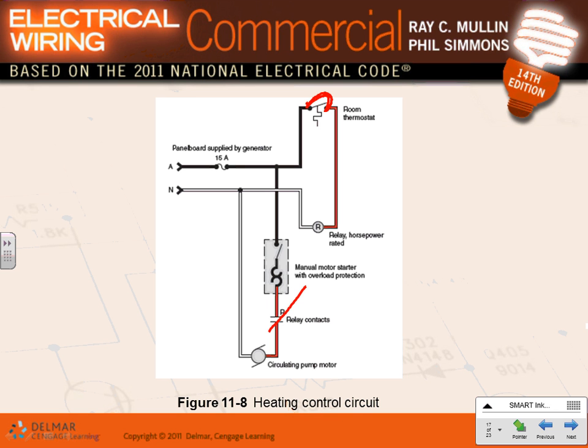So first the thermostat has to call for heat, close the coil. Now the coil is energized. This will close the contact. Now the pump is pumping hot water into the insurance office. Inside the insurance office, guys, it goes to a radiator. It's like a radiator. Then there's a fan that blows air right through it, and you got yourself hot air, or an air handling unit. In our project, we have an air handling unit. We circulate the hot water to the air handling unit. Inside the air handling unit, a big blower blows air right through it, and from the other end, you get hot air. Can I have thumbs up, Chad?